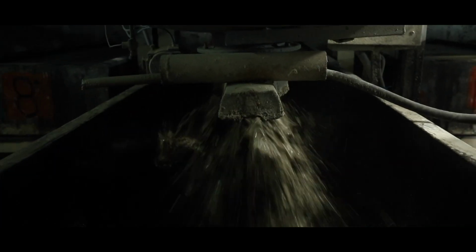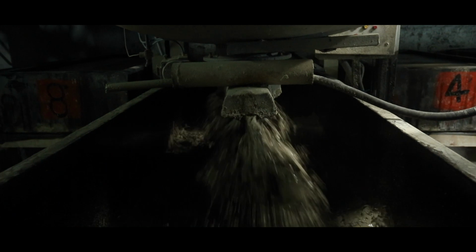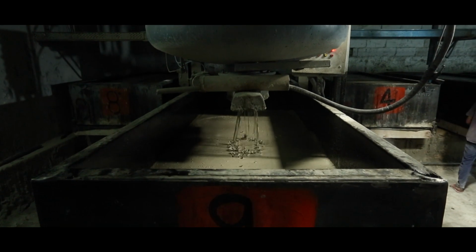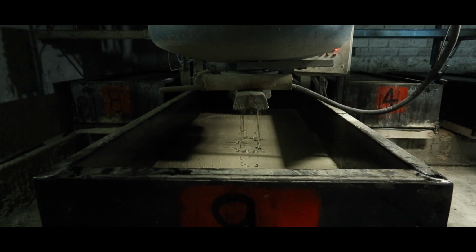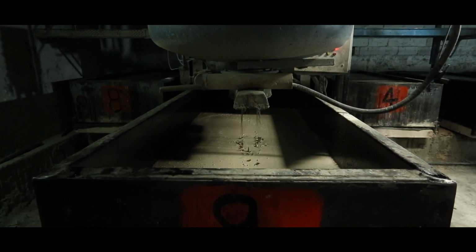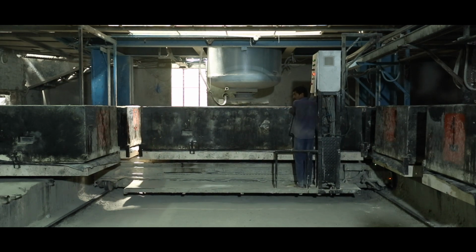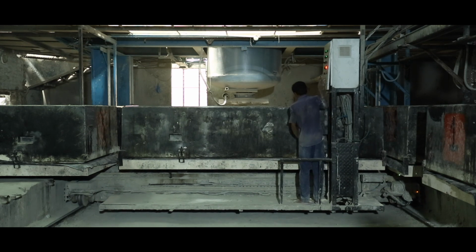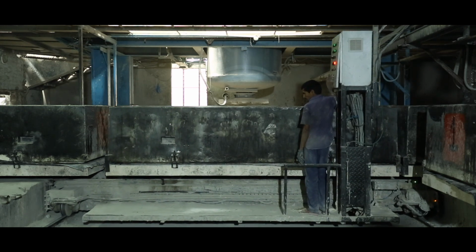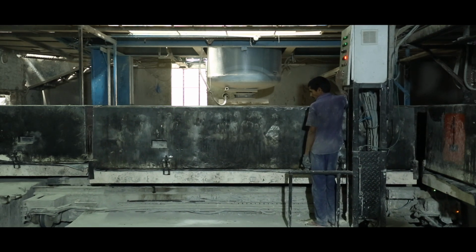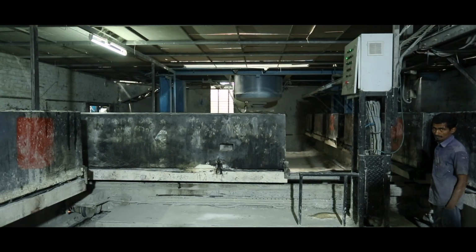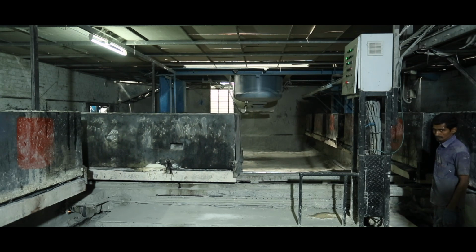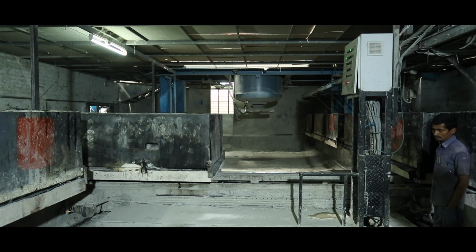After mixing of slurry in the high-speed mixer for a preset time, the slurry is poured into molds. Once the slurry for cake formation is emptied into the mold, chemical reaction takes place at a particular temperature within, resulting in aeration, thus causing the cake to swell and rise. The mold comprises of a bogie on wheels with detachable base and sides. The slurry-filled molds are kept in the preheating area first and then shifted to a parking area through a transfer car and pushing arrangement.